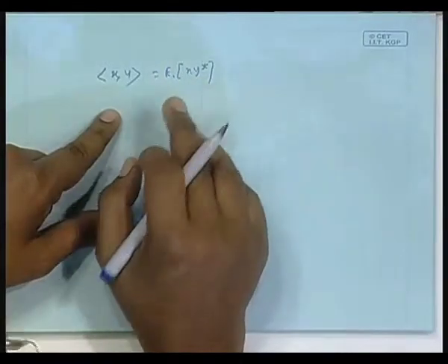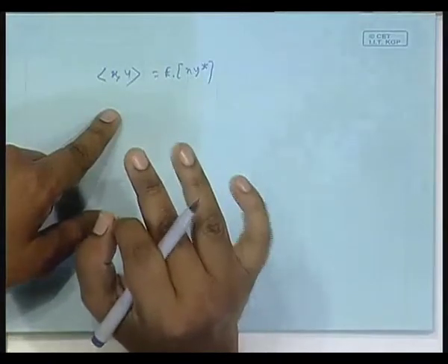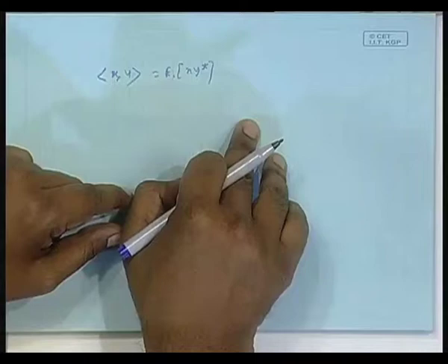But I want orthogonality and uncorrelatedness to have a physical meaning. Orthogonal means just orthogonal. But if it is 0 mean, it also means uncorrelated. Then there is a physical meaning that comes out: the random variables have no correlation amongst them. Otherwise, it is pure mathematics. Orthogonal means correlation 0, but if you make it 0 mean, it is also uncorrelated. So uncorrelated has a solid physical meaning: two variables are varying purely randomly without any relation between them. I want to make use of that so that you get a physical meaning of, say, white noise and white process.